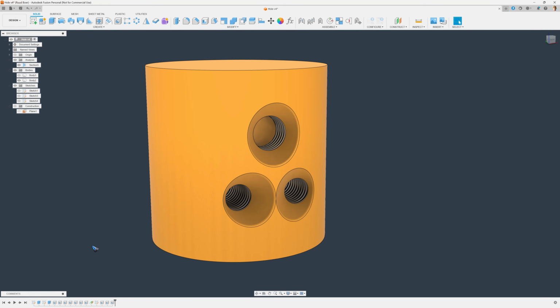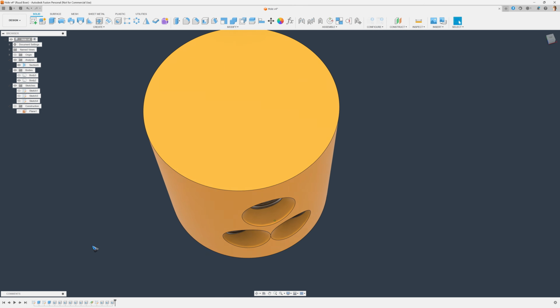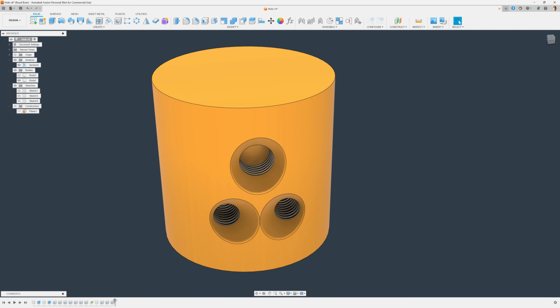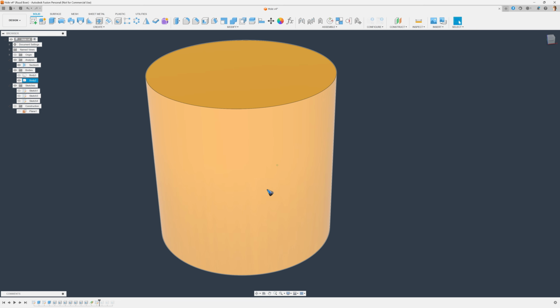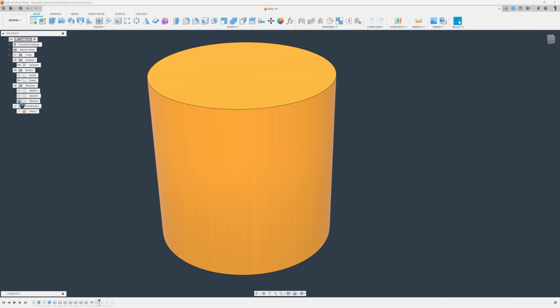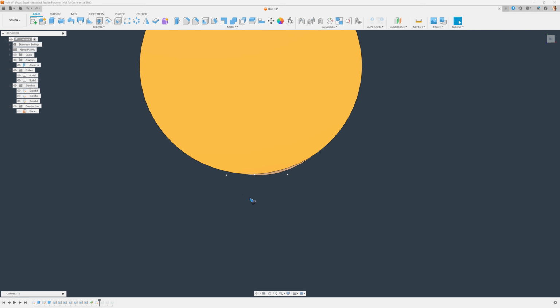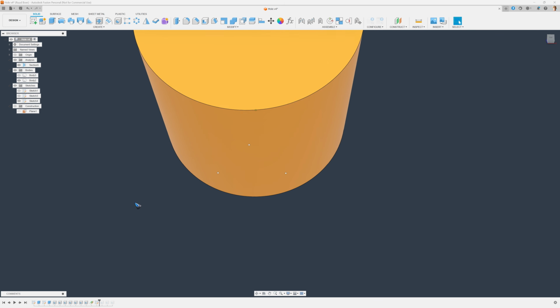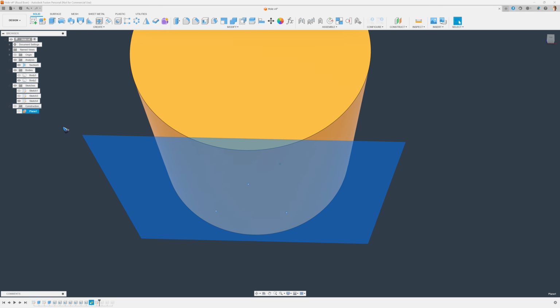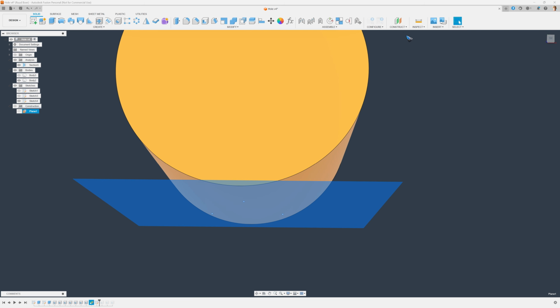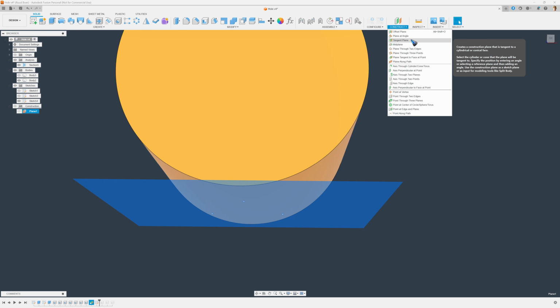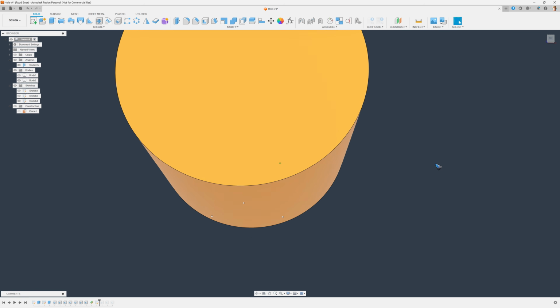It is perfectly okay to drill holes in a round object or a curved surface. In that case we will need a sketch, so let's have a little look at how these were made. We have a curved surface. I did make a sketch, but you cannot make that sketch on a curved surface. As we can see, the dots that I use are on a plane, and this plane was made with the function construct tangent plane. Then you select the curved surface on which you want to make the tangent plane, and there you have your surface to make your sketch on.